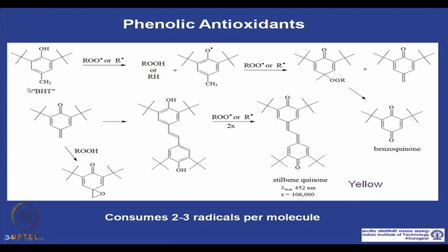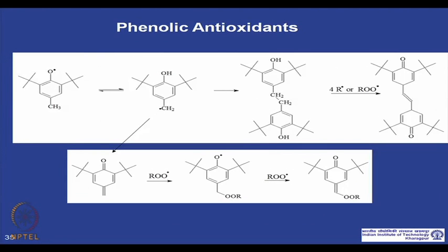So, these additives themselves do not discolor the polymer, but the final compounds formed after stabilization could generate color in the polymer matrix. That is one drawback, and each molecule basically captures 2-3 radicals, by which they prevent this oxidation process.